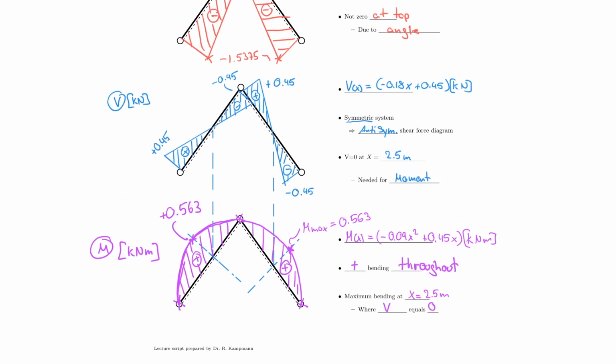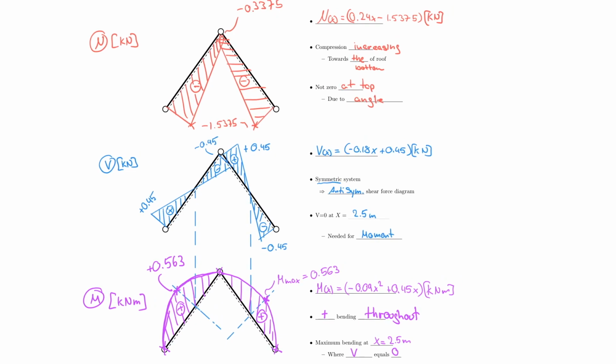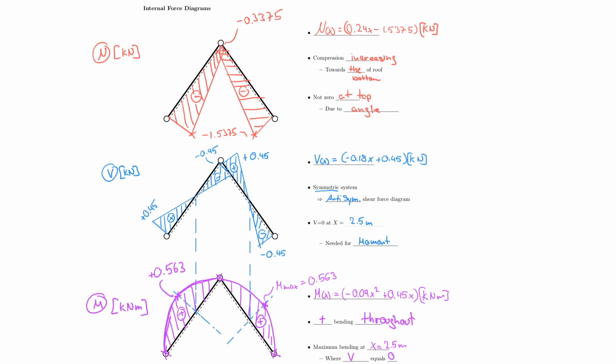because think about it, the snow is just a different way of self-weight on the system. I mean, it's not self-weight, but it acts like self-weight because both of them are actually attracted to the center of Earth, which, by the way, will be different for the next case we're going to talk about, which is wind load. But I will talk about that in a second. Before we do that, let us discuss these again. So normal force increasing downwards, like every piece of snow adds more and more weight here until it's supported. And so this graph makes perfect sense.